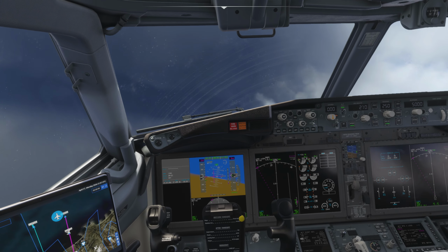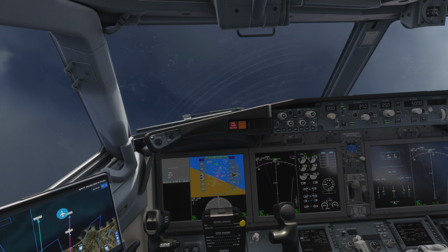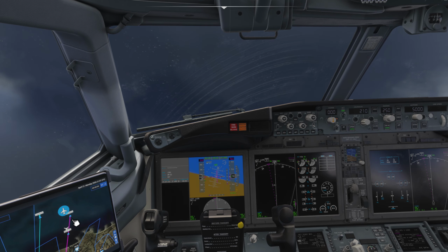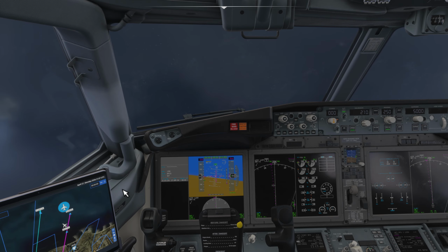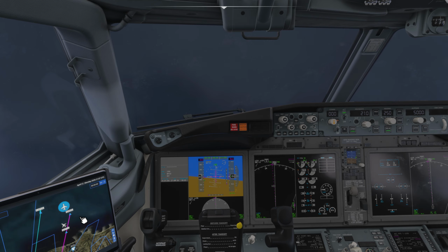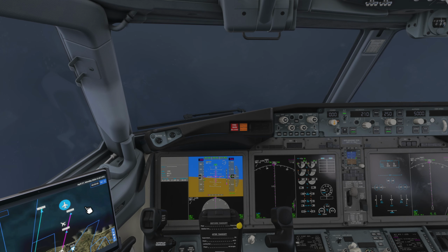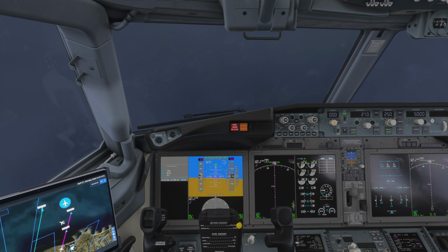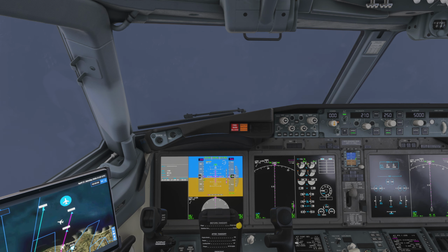Basically, we're going to do a full 180 degree turn to get her lined up here with the first waypoint of the glide slope. And our goal is to have the ideal altitude, 2,000 feet, and the ideal speed, so that she'll talk to the airport's localizer and start communicating with her.